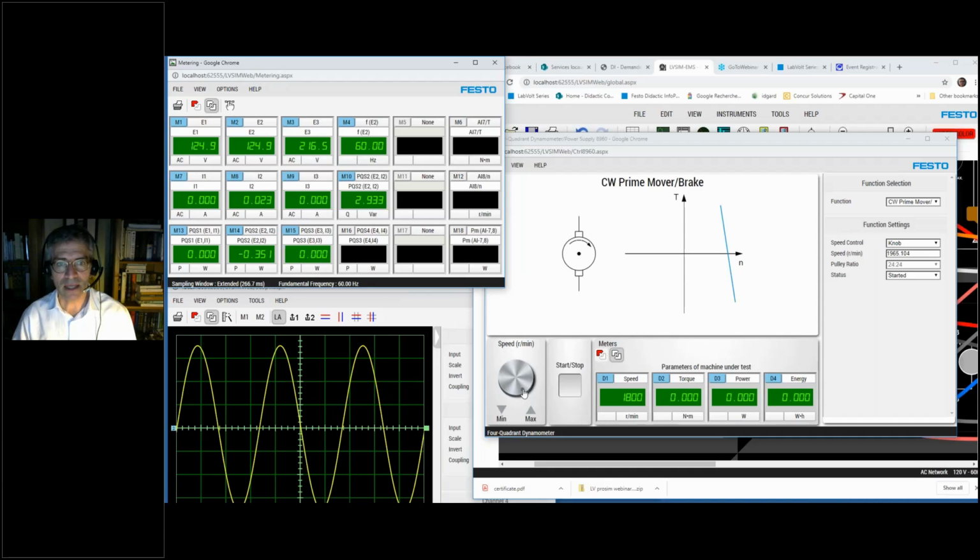So you will see now that as I try to change the speed of my generator, since the speed cannot increase, what I am doing, in fact, is increasing the mechanical power I put into the generator, which turns into electrical power. As I increase the speed setting here, I put more and more mechanical power on the generator, which produces more and more electrical power for the network. I remind you that this is the power generated on a single phase, so this would be multiplied by 3 for our 3-phase output.